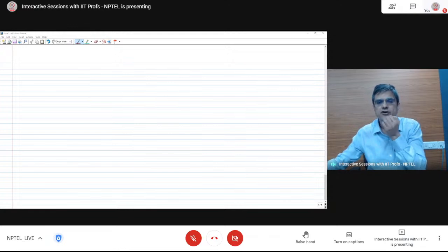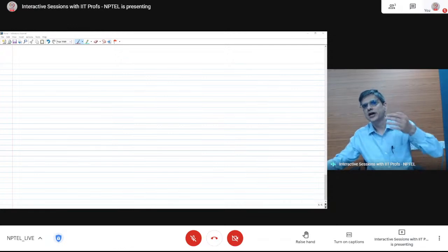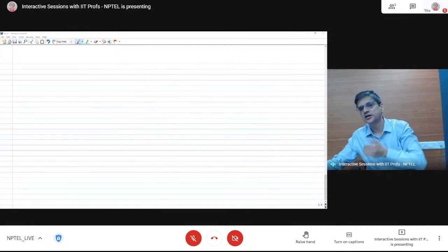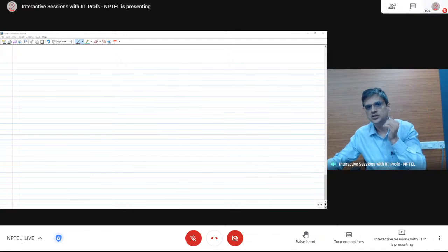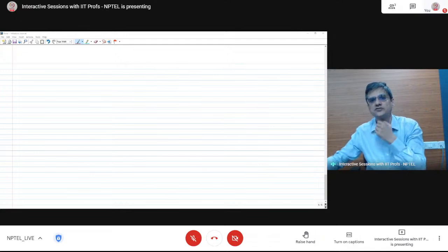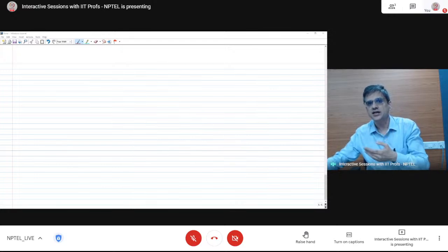If you ask me a question like, okay, I have a 10 by 10 system and these are the 100 transfer functions, I would want to convert the transfer functions into step response coefficients. The question that a lot of people will ask is, why did you even convert them into transfer functions? We don't naturally get transfer functions.